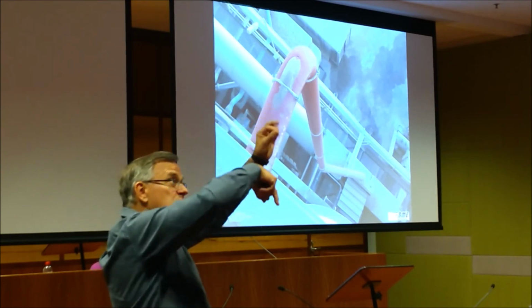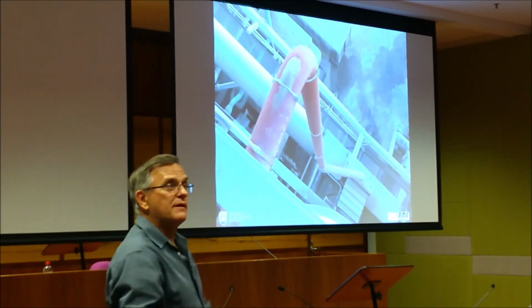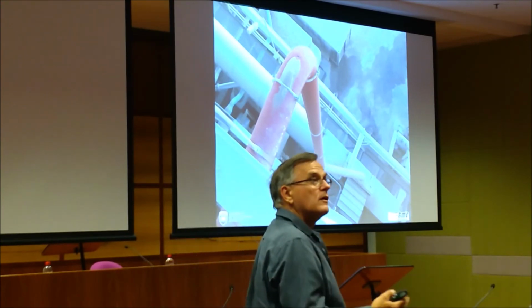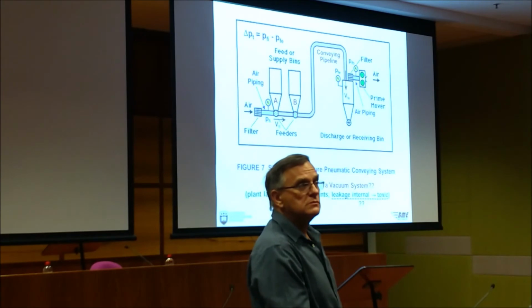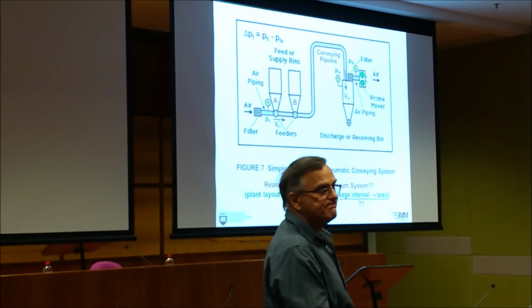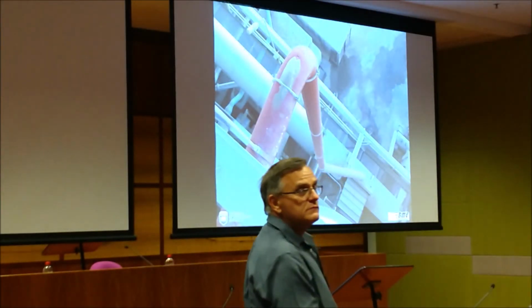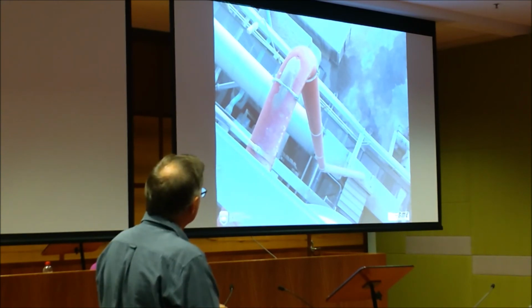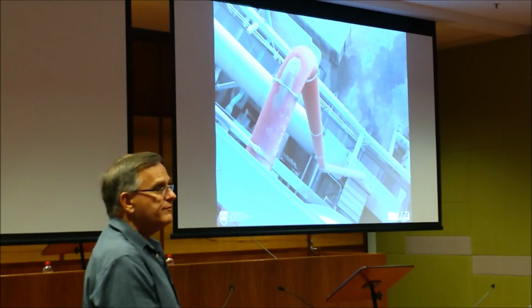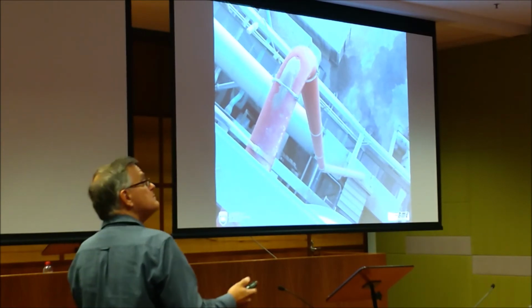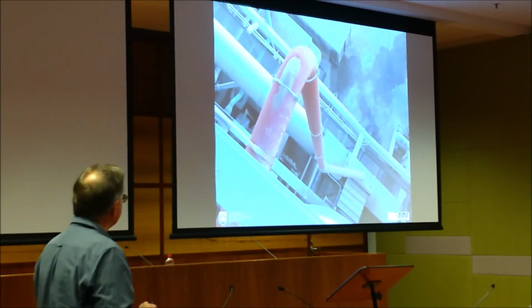The air's being sucked in, but the particles are heavier, and they get past the air, no problem. So this issue here is questionable. You cannot rely on it 100%. And there's the proof. Those particles have come from that hole. It's quite obvious. So don't always believe what you read out there, be careful.